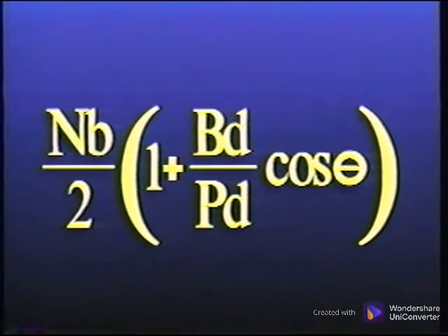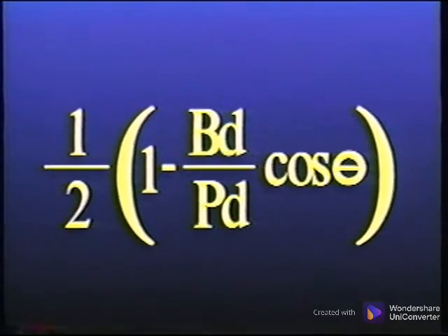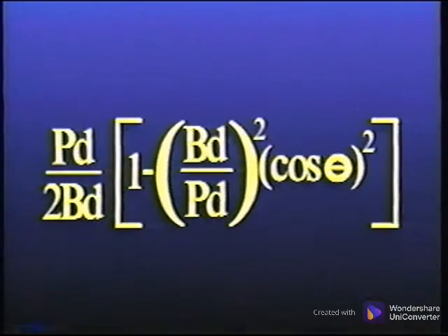This is the equation for calculating the inner race. This equation is used to calculate the fundamental train frequency or cage. This final equation is used to determine the ball spin frequency. Remember that these equations give the frequencies in orders exhibited by defects in the individual components.